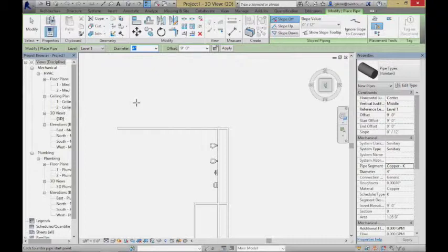So if I have a bunch of toilets which are hanging around about 18 inches off the ground, I want this pipe to be pretty low to the ground, or maybe even under the floor level. Sometimes it's in the ceiling of the floor below or something like that. But to have a sanitary pipe work, I have to get it pretty low relative to the toilet. If I try to run the pipe right up here at the same level as the toilets, it'll probably be okay for the sink and for the urinal, but there won't be enough room to put all the elbows and the connections in to keep everything running downhill.